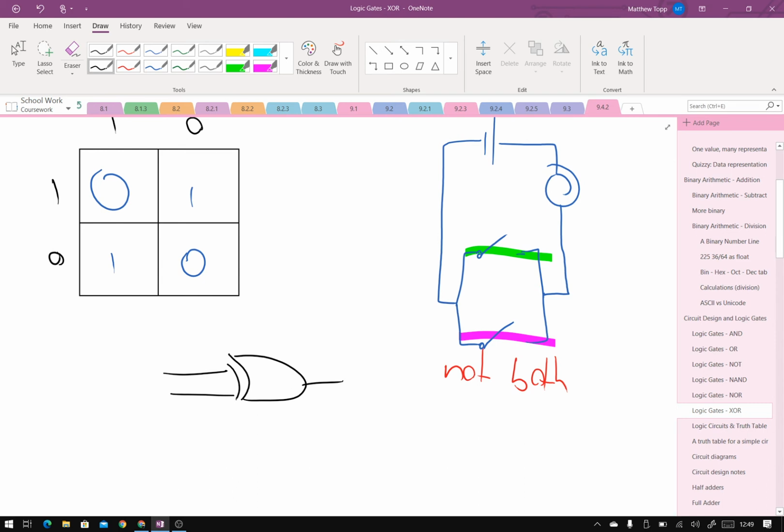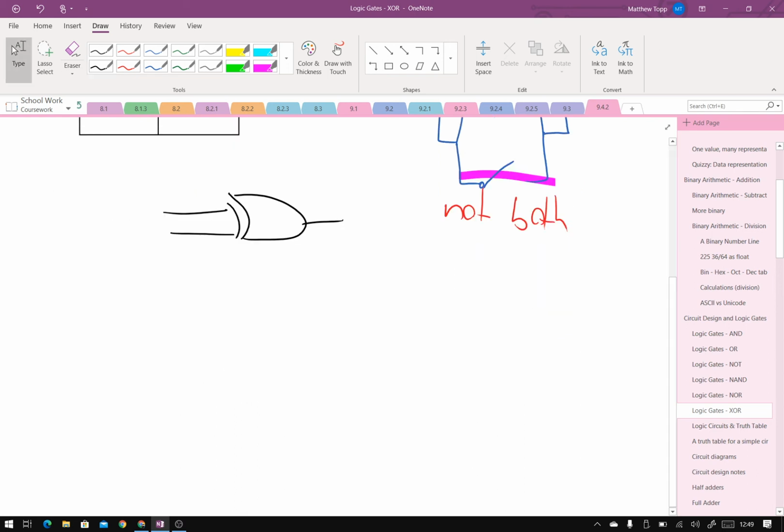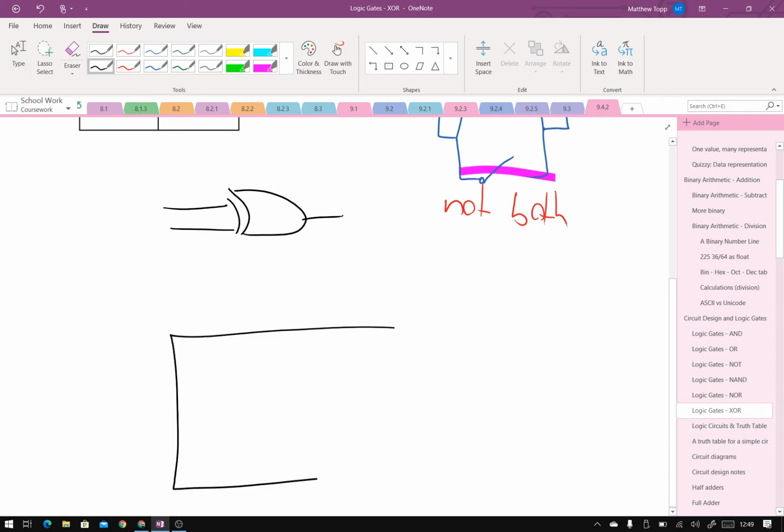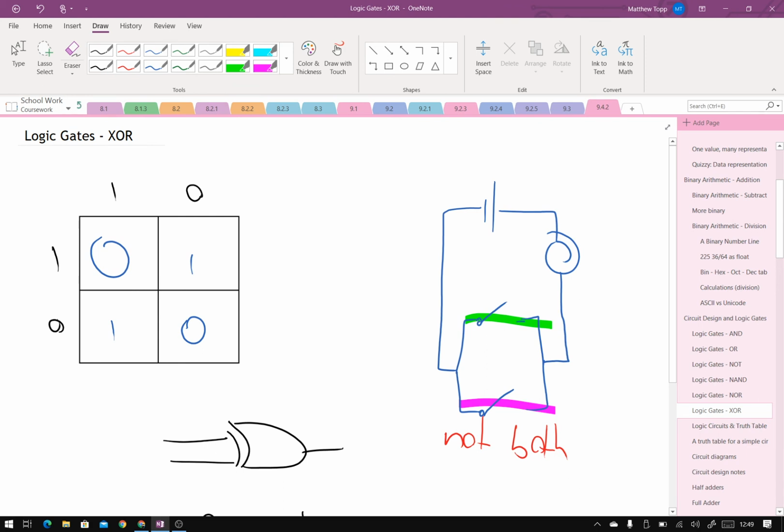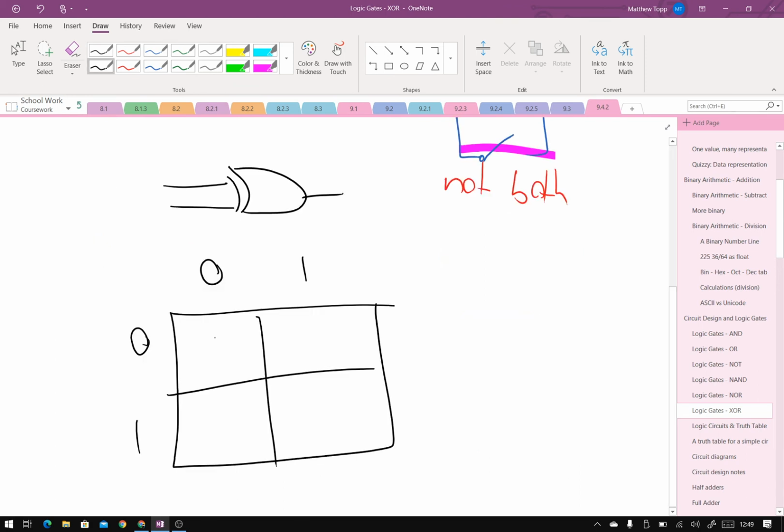Now, you should think to yourself, hey, we could do a seventh one straight away, because I've got my XOR gate, and I've got my logic here. Isn't it XNOR? We could do an XNOR gate, exclusive NOT OR gate, which would be a straight inversion of that. So exclusive NOR. I got my zeros and ones back to front, haven't I? It doesn't actually matter when you're drawing the truth tables, as long as you draw them separately. So I'd be doing the exact opposite of that. So it's 1, 0, 0, 1 for an exclusive NOR.